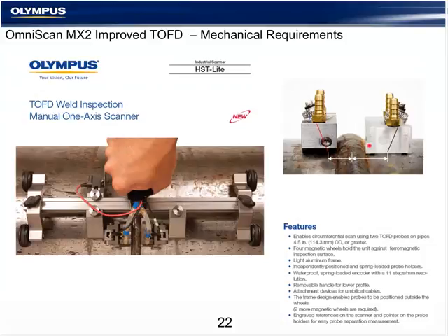The new wedges that you see, the stainless steel wedges, will allow us closer access to the welds for near surface coverage, eliminate the need for mechanical feet, and provide a better, more stable platform for the TOFD data, with less of the hassles that come about from the lateral wave distortion from the mechanical feet that are required for Rexolite wedges. And again, a simple water supply here, and these probes are marked for the exit point, so it can easily be seen for measuring the PCS.